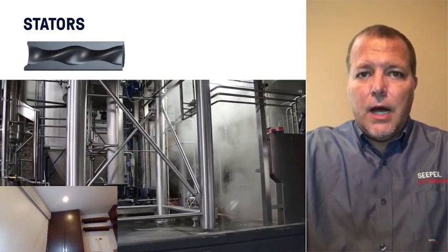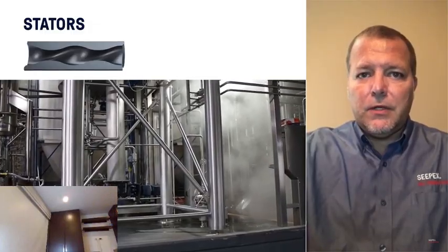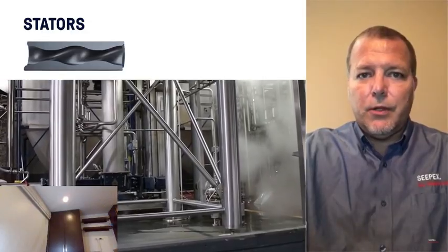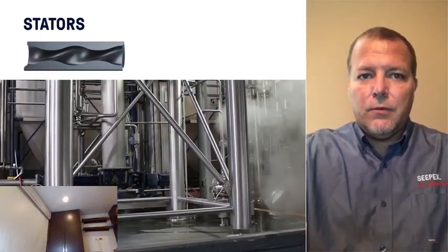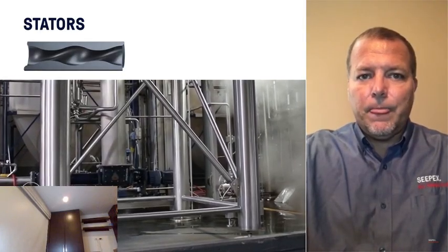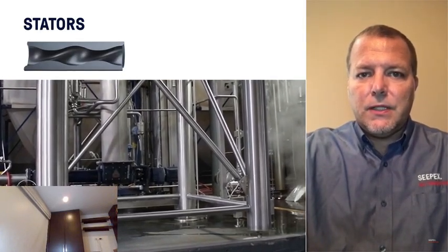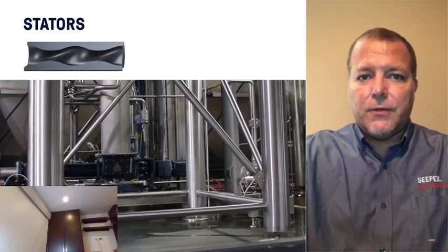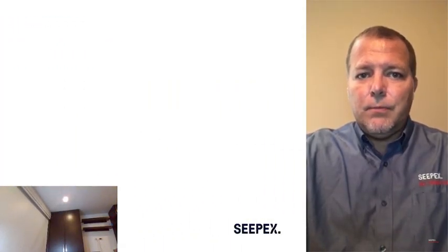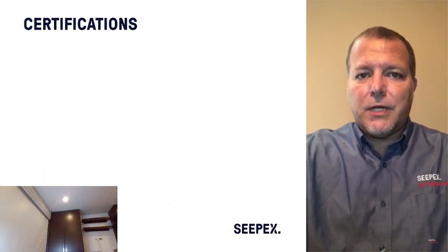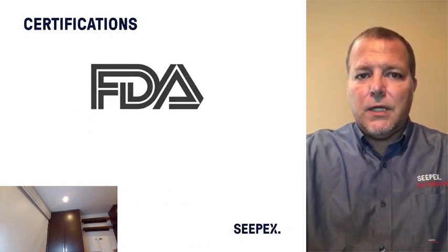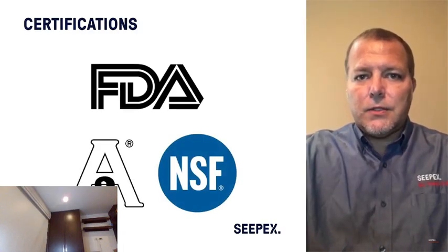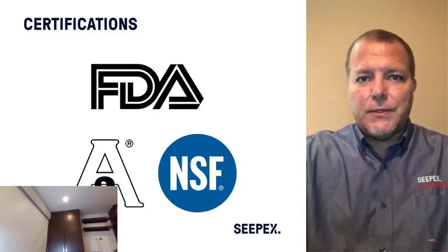Temperature. High temperature will cause swelling and failure of the elastomer, stalling of the pump, or damage to electric motors from the increase in compression and resulting high torque. For high temperature conditions, consider an even wall or even a split elastomer design that can allow for expansion. Some PC pump companies have special certifications such as FDA, 3A, even NSF for drinking water. Ask your PC pump company for options.